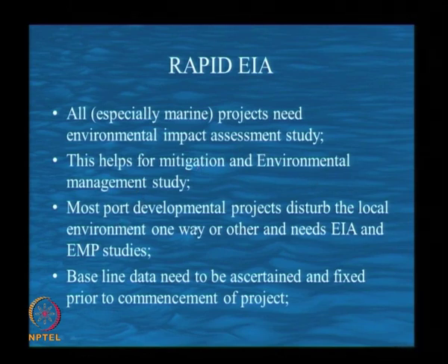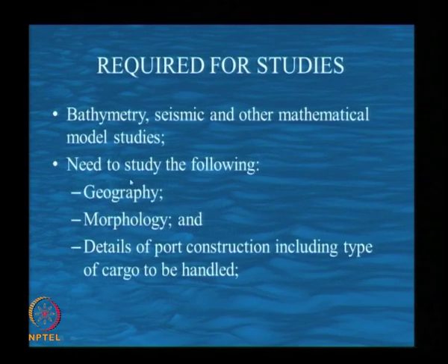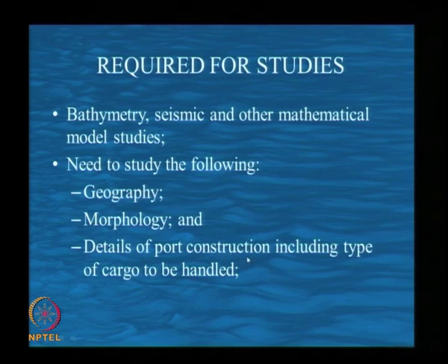So, most port development projects disturb the local environment one way or other and need EIA and EMP studies. So, important is baseline data, this is to be ascertained and fixed prior to the commencement of the project. What are the studies that are required? We already studied this bathymetry, seismic and other mathematical model studies, and we have to study the geography, the morphology and the details of port construction, including type of cargo to be handled.